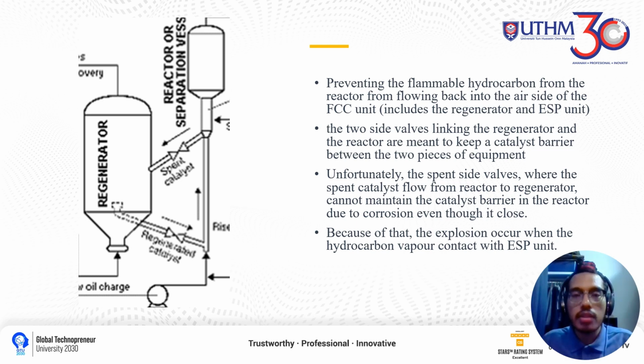So unfortunately, the spent catalyst side valve, where the spent catalyst flows from reactor to regenerator, cannot maintain the catalyst barrier in the reactor due to the corrosion, even though it was closed. Because of that, the explosion occurred when the hydrocarbon vapor contacted the ESP unit.